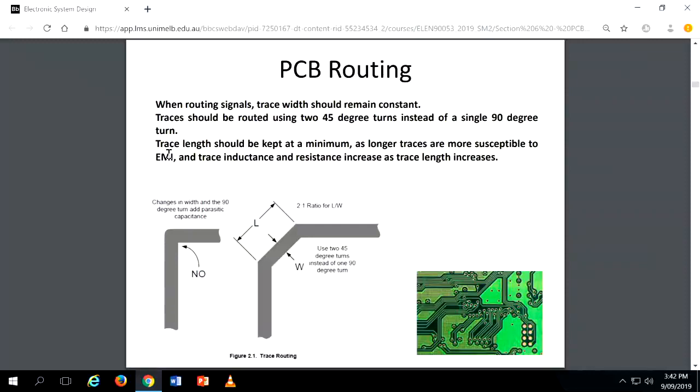Then the question. When I was a student, I asked the same question: if I make 90 degrees, what is the problem? If you make 90 degrees in low frequencies, it is not at all a problem, but that is not professional. Nobody will design a 90 degree bend. Then at high frequencies, definitely a 90 degree bend is a problem. For example, in high frequencies, the signal behaves very differently. Some students get confused when somebody asks, I will make a 90 degree bend, what is the problem?